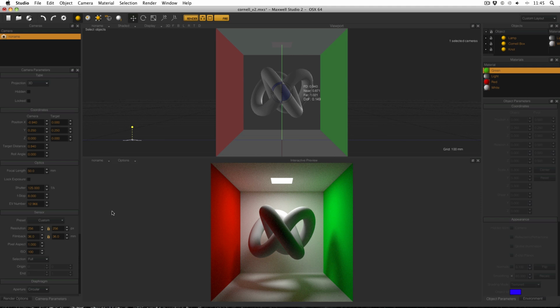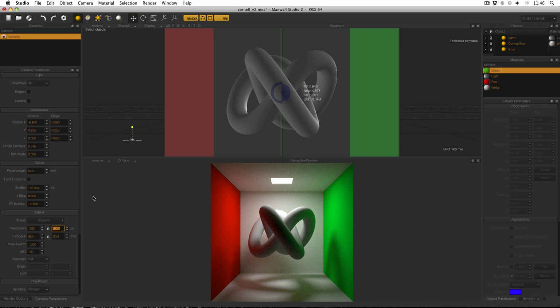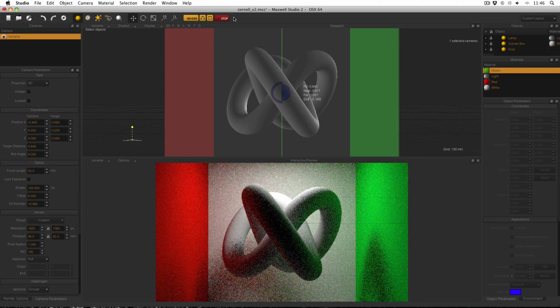Now I'm going to cover desktop resolution first, and for me at the moment I'm working with a full HD display, 1920 by 1080. So what I'm going to do is, on resolution on one side, keep the aspect ratio locked, because, why not, put 1920 and then enter, and then unlock the aspect ratio and then put 1080 on the other side, and you'll see it'll zoom in a little bit. I'm just going to engage fire again. Don't worry about that. That's just because the aspect ratio has changed. It's still technically the same view, but it's sort of cropped out the top, if you like.